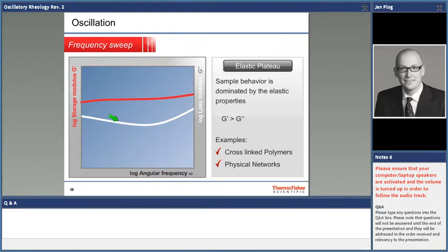The one with the lower G double prime, meaning the lower tan delta, will be the stiffer system, not so deformable, meaning that when it breaks, it will fracture not so nicely. You have a lot of splinters flying around. Okay, the better deformable, the better damped polystyrene, for instance, would be the much better material to formulate a bumper material.